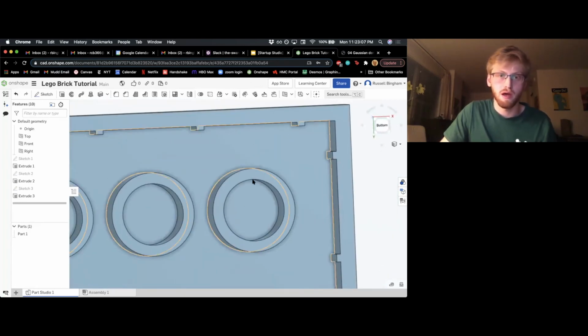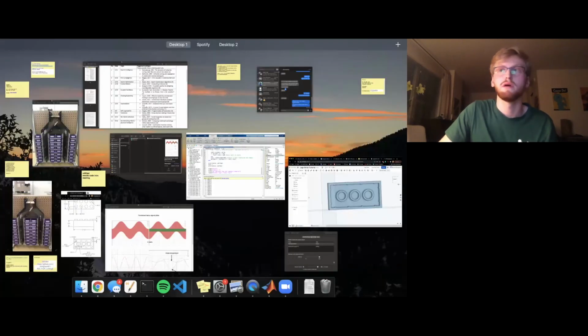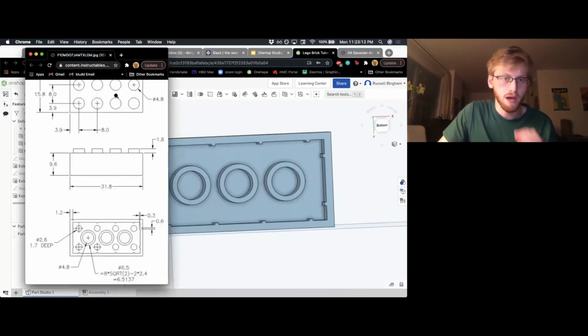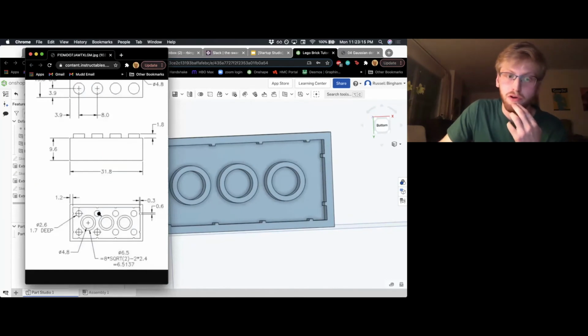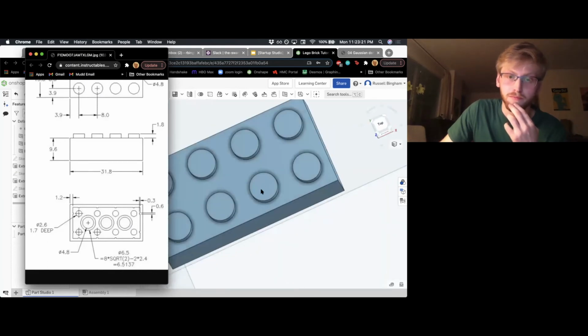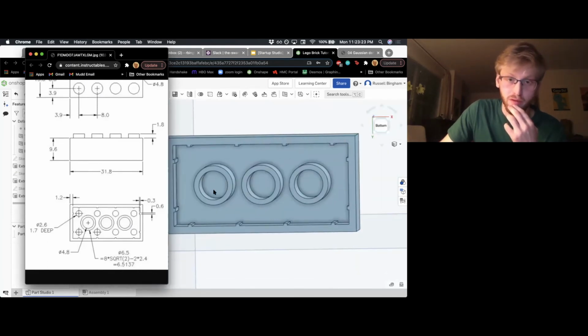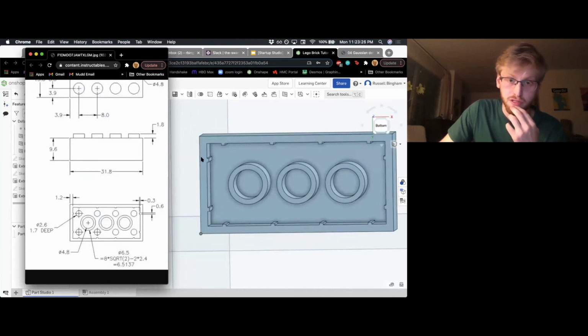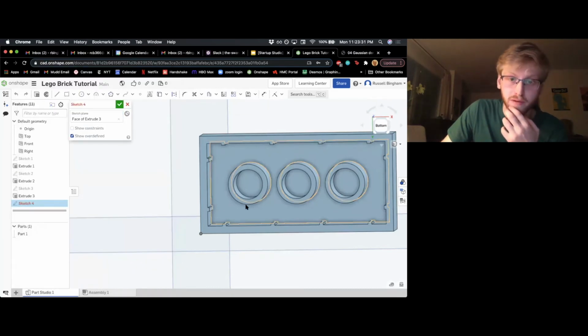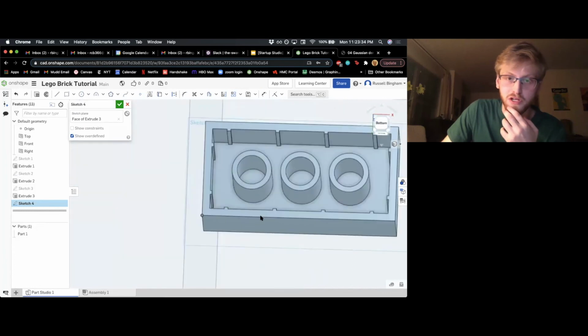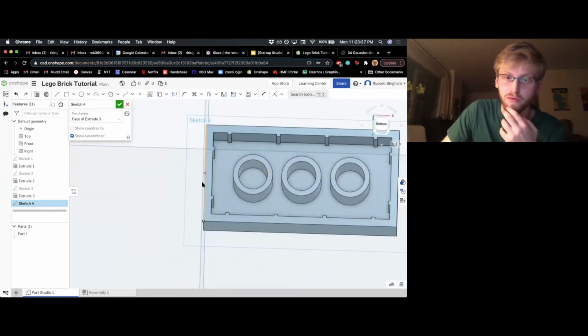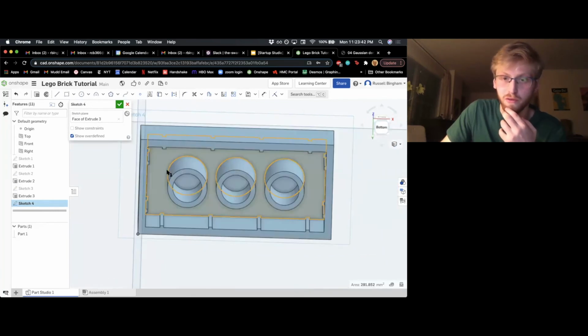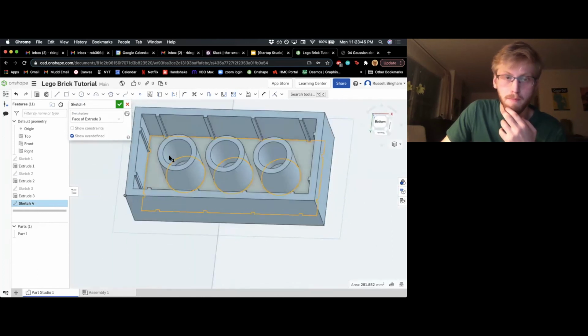a little tiny thing, if we go back to our drawing, here we go. I'm going to add these little holes here, and these are centered under the holes up top. So these are 3.9 millimeters again from the outer edge, this edge here. But when we sketch on this bottom plane, you're only sketching on this surface here, and this surface doesn't know that there's a wall on the outside here. This contiguous surface is the only thing you can draw things on.